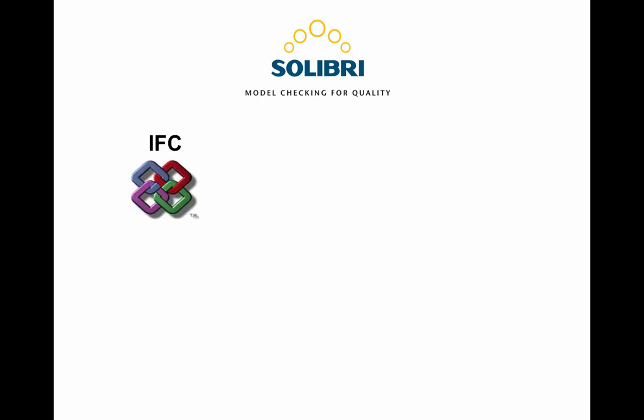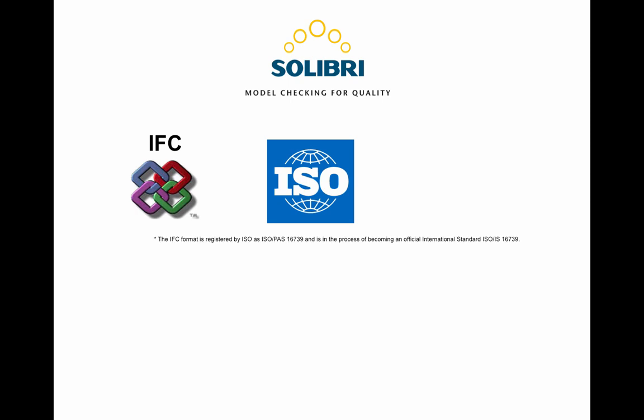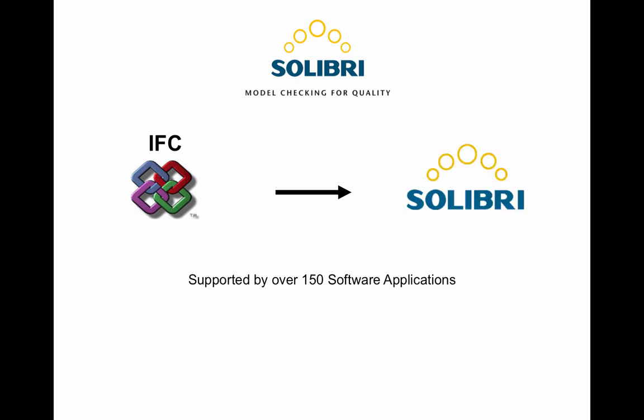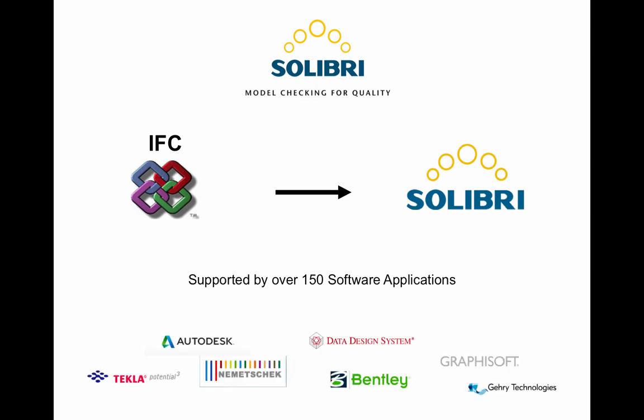The data utilised to generate models for checking are created via IFC, Industry Foundation Classes, a model data exchange format developed and owned by Building Smart. IFC is an ISO international standard which the UK government sees as key to achieving its goal of Level 2 BIM by 2016. IFC models created can be imported directly into Solibri Model Checker. IFC is supported by over 150 software applications. For a full list of applications that support IFC, please visit the Building Smart Tech org site or follow the link on screen.